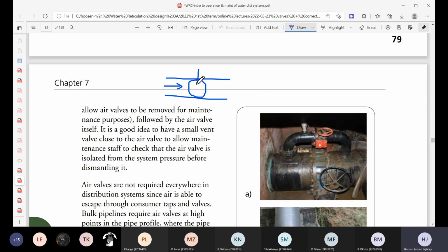If you were to close this thing, so if you had a handle here, that's the handle you see in the picture there. If you turn the handle 90 degrees, it would then close up like that. So you'd see that circular plate. Now you look at it, it'll just be like that, and it shuts off flow in that particular pipeline. So that's a butterfly valve.